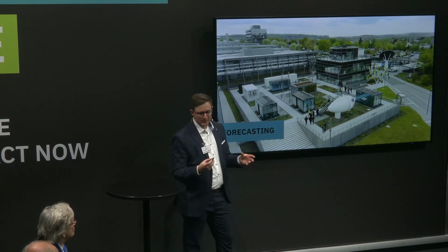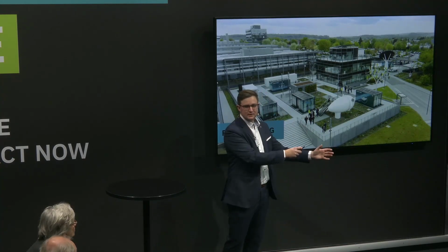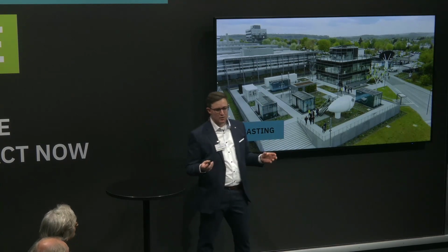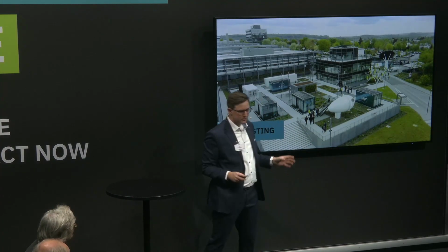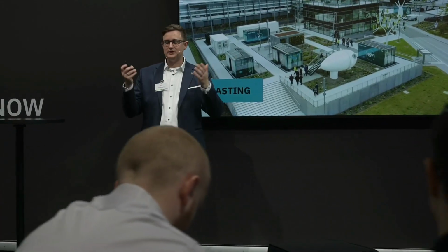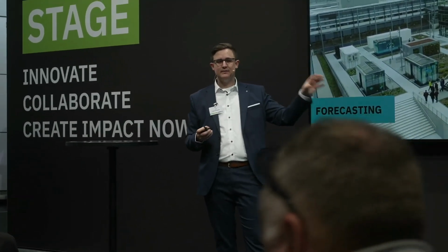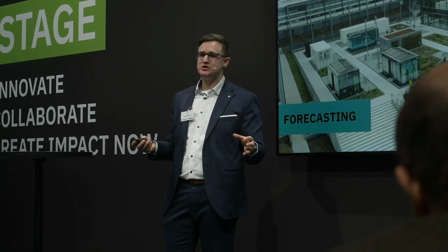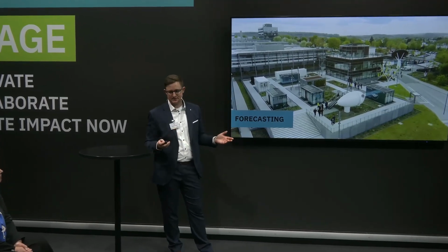And this is maybe very important for sector coupling. Maybe I have my production, I have my EV charging park, and I also have my photovoltaic, and I want to know when to use my electrical battery storage, when to charge my EVs, and when I need all of my energy for production only. Because let's be honest, we need to ensure that production can run 24/7. So with the energy forecasting in MLnext, we can decide at which time points it is most beneficial to, for example, load our battery or the car, to have a good energy demand analysis.